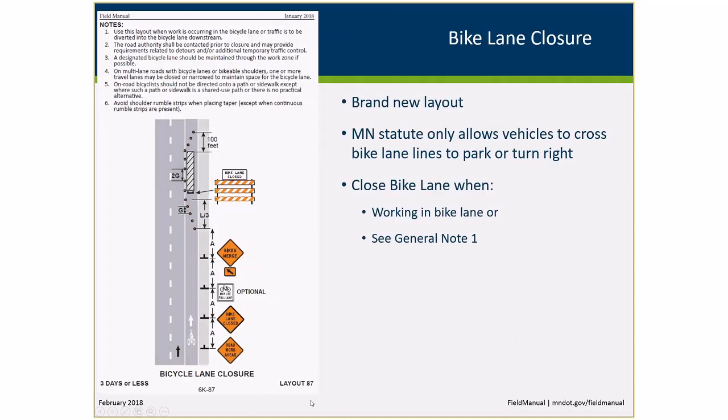We added a layout for a bike lane closure for a couple of reasons. There's a Minnesota statute that only allows vehicles to cross bike lane lines to park or turn right. If you happen to have a job downstream of here and for some reason you need to send traffic into that bike lane, you can't do that unless you closed the bike lane. So this layout is to be used when you're working in the bike lane, or, General Note 1: use this layout when work is occurring in the bike lane or traffic is to be diverted into the bicycle lane downstream.